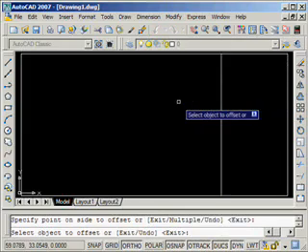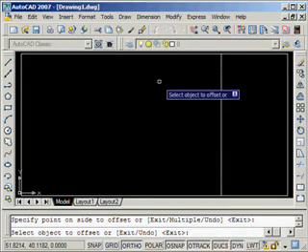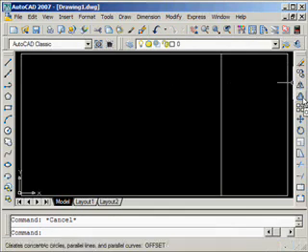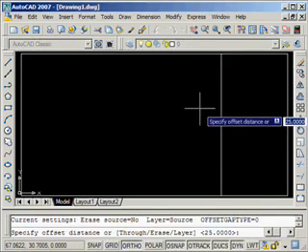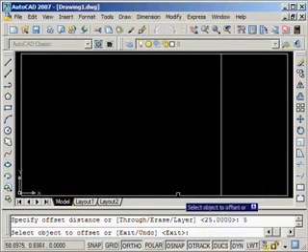So I'm going to click over to the left here inside my property line, and you can see it drew a new line. To exit the command, I'm just going to hit escape a couple of times. Now I'll choose offset from the toolbar, and my house has 5 feet between it and the property line, so I'm going to choose 5 feet.